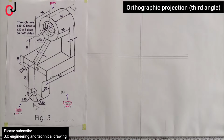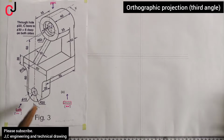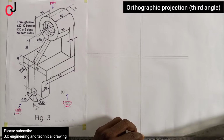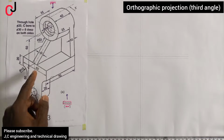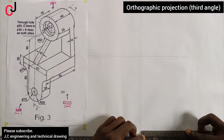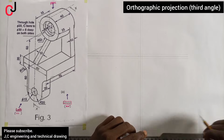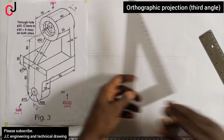And also I'll indicate the center line, which is 30 millimeter. Since the total length is given to me as 60, so the midpoint is 30 millimeter. So I'll measure 30 millimeter and then I'll indicate the point. And then I'll project my points upward with a center line.